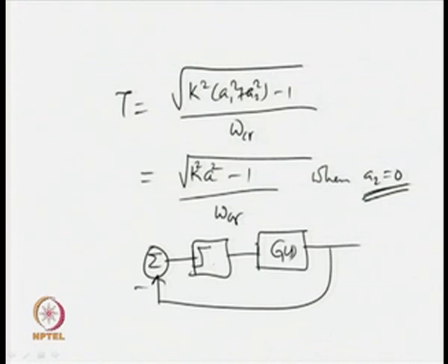So, for this case we do not have any controller either in series or in parallel with the relay. In that case A2 becomes 0, because if you look carefully, A2 can be expressed in terms of Kc times certain things, and Kc will be equal to 0 when there is no controller in the relay control system or during the relay experiment.